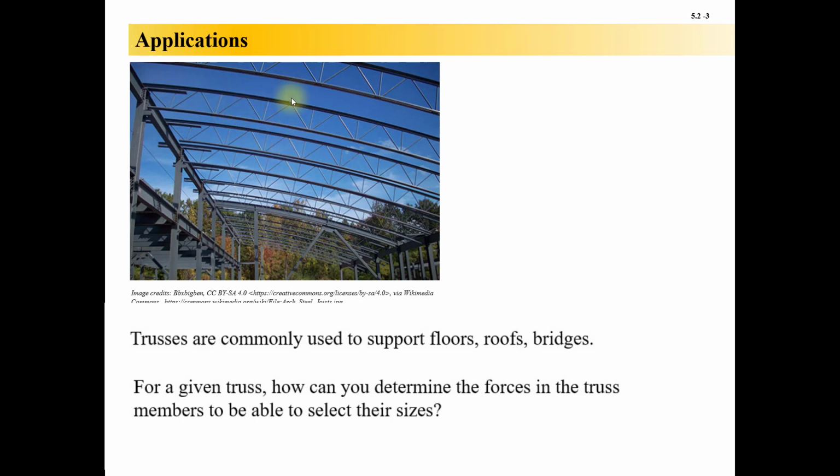These trusses here look quite a bit different than this big truss back here, which is part of the lateral force resisting system for this building, like against wind and seismic, where these are just holding up the roof itself. So the moral of the story is somebody's got to be able to figure out what the forces are and then size the members accordingly.